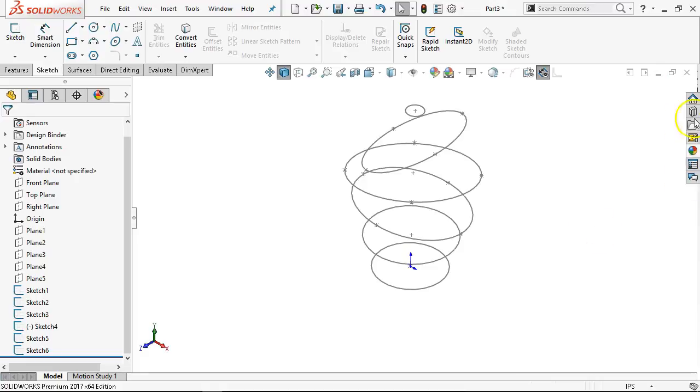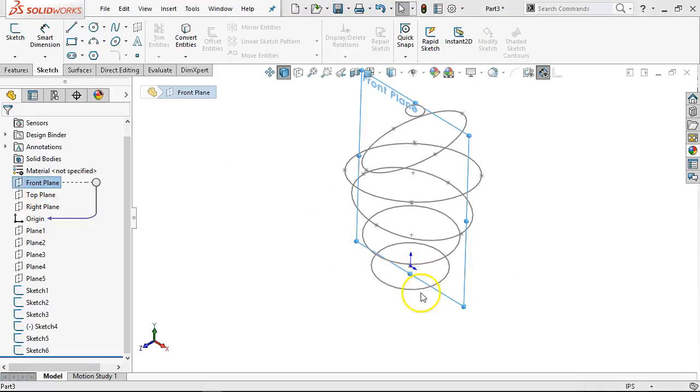Okay, so if I do nothing with the guide curve, and typically I would like the guide curve to keep it nice and simple, through the front plane it goes from intersecting point to intersecting point to intersecting point. Oops, I'm not quite at an intersecting point, at least on the node. I can probably get there, but if I want to be able to control it, then I could go through the 3D and connect that point to that point to that point. Each of these ellipses has 4 points.